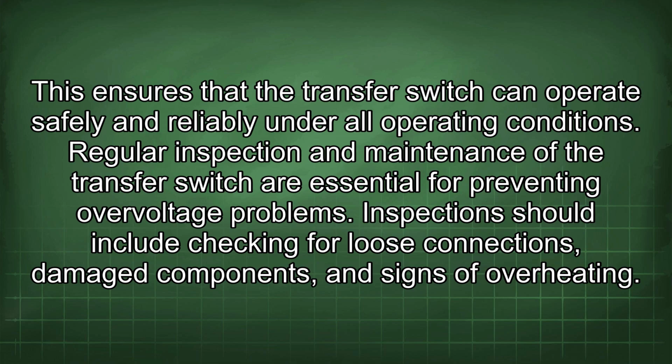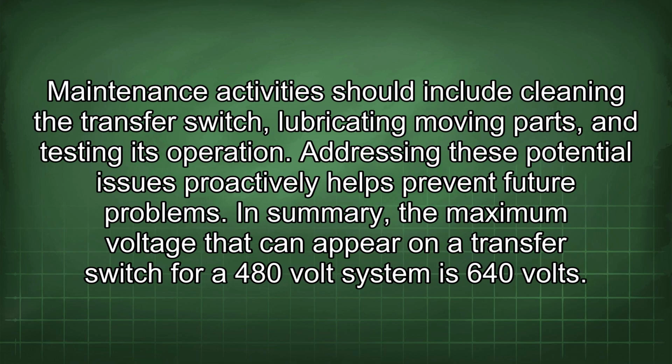Regular inspection and maintenance of the transfer switch are essential for preventing overvoltage problems. Inspection should include checking for loose connections, damaged components, and signs of overheating. Maintenance activities should include cleaning the transfer switch, lubricating moving parts, and testing its operation.